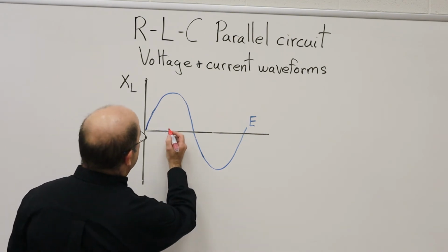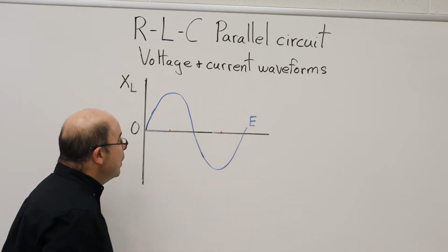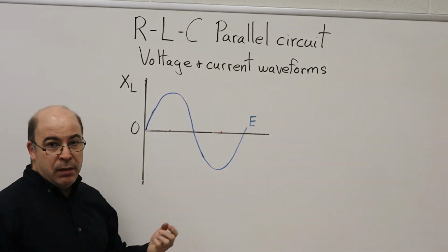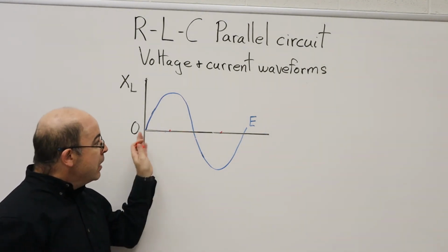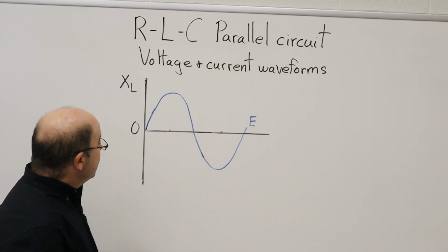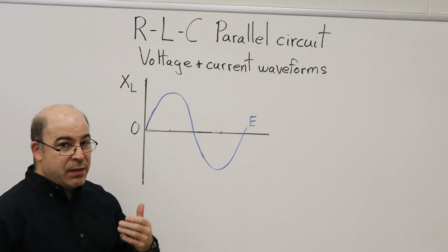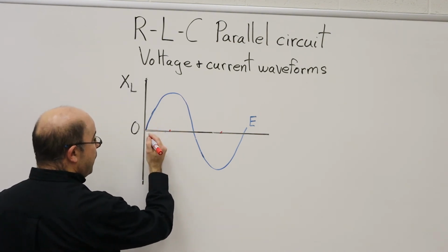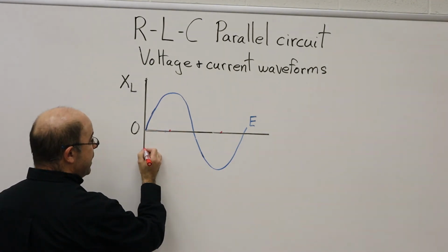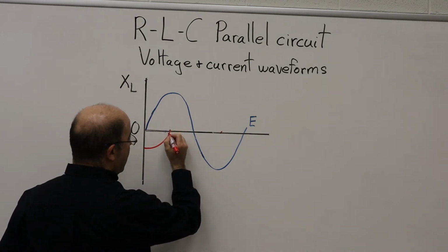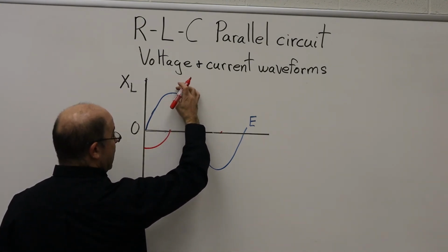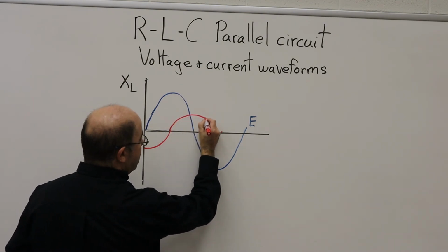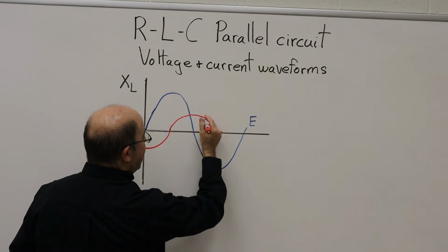So having measured this previously to turning on a camera, there's about the midway point. So this represents a half of alternation, and the midway point is 90 degrees, the midway 180, one full alternation is 360 degrees. So it becomes very easy. Now, because the current lags the voltage, I am just going to draw it here in the negative alternation, because voltage, if it's at 0 and current lags, it's going to have to be down here. So we're going to draw this out, cross where the voltage is at its peak. The current will be offset by 90 degrees, and we're going to continue this trend. Try and be accurate as I say that.